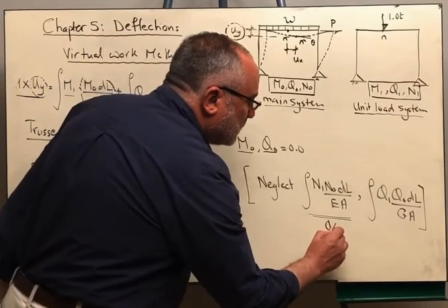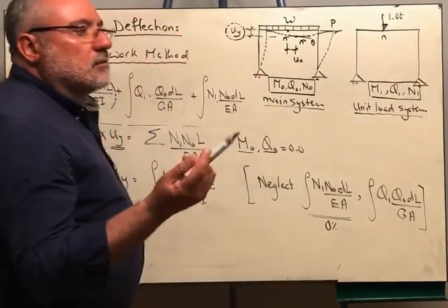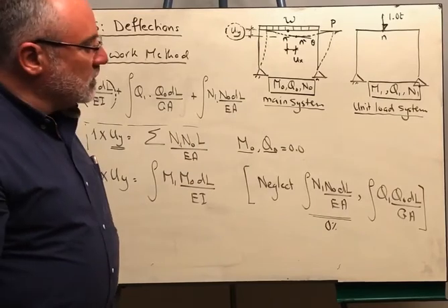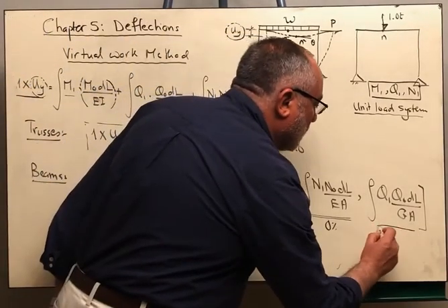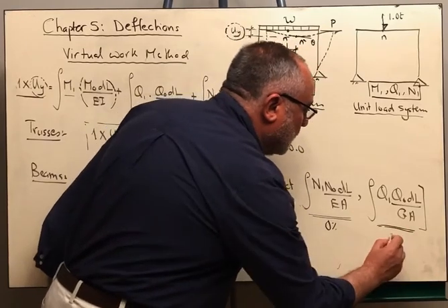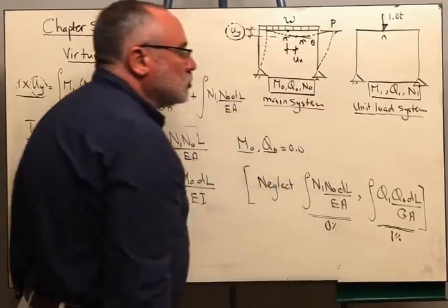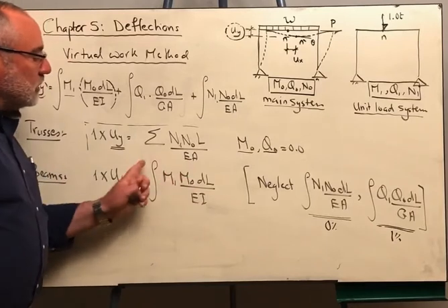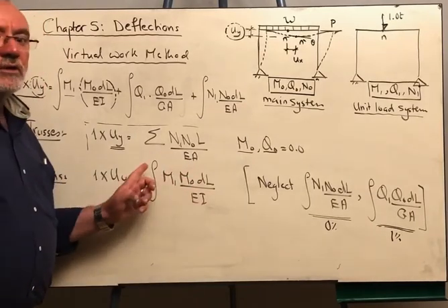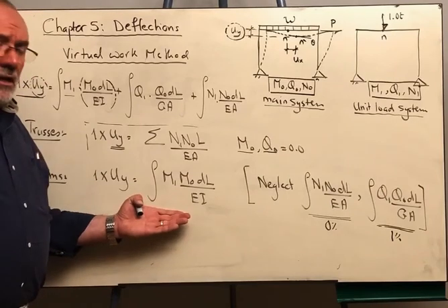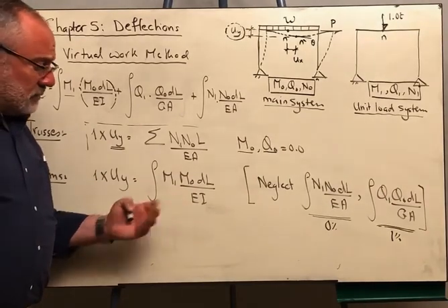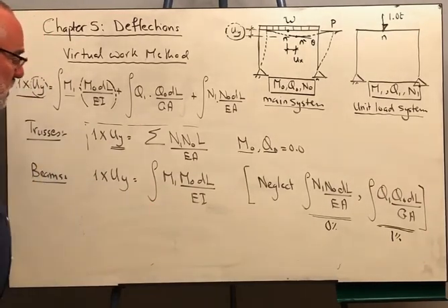It might be 0%. Already we might not have normal force in the first place, and also the magnitude of the deflections caused by the shear is very small. Maybe it constitutes 1%. So 99% is caused by the moment and the rotations associated with it. Therefore, in the deflections of the beams, we are going to use this equation.